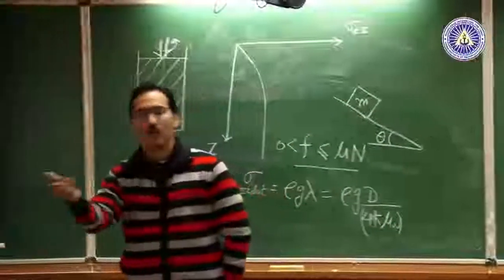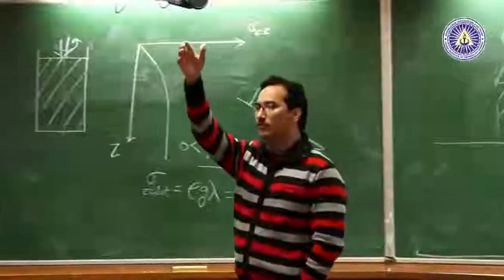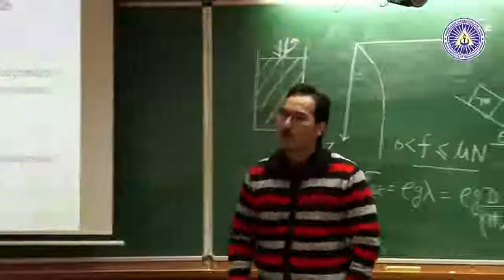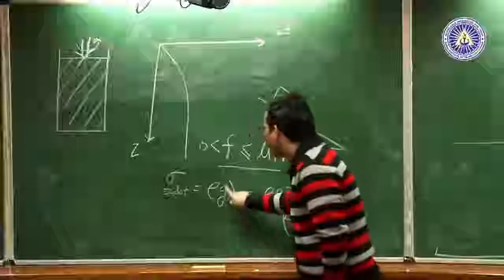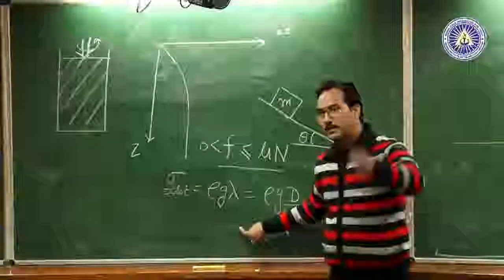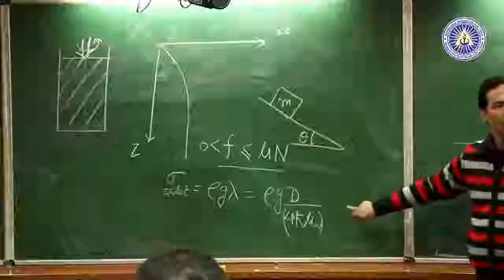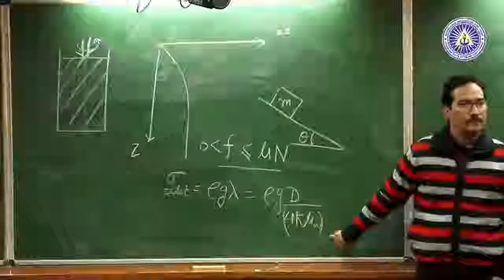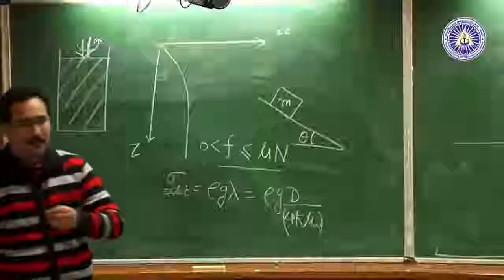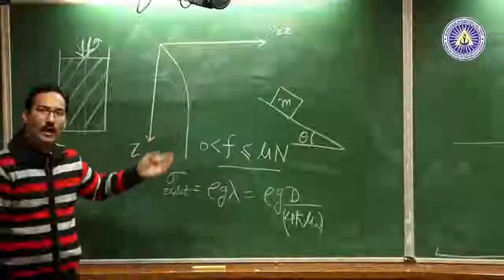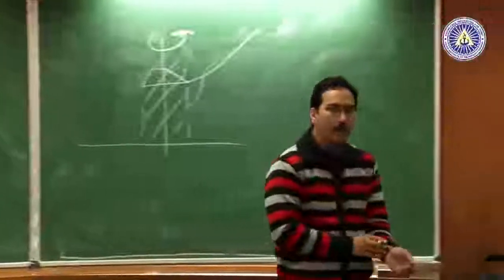And so you might want to try what you typically would do for a fluid, right? You would expect velocity to be proportional to, in that case you assume hydrostatic variation and say velocity equals root 2gh. The velocity at the exit, assuming Bernoulli's, is root 2gh, except that now, because the pressure is no longer hydrostatic, instead of h I can use this lambda and try some correlation. Is everybody with me? Is everybody following what I am saying? I am trying to connect the constant flow rate through the orifice with the constant pressure that we observed yesterday, and see if there is a connection between the two, because that's an obvious connection a fluid mechanics person would like to make, right?